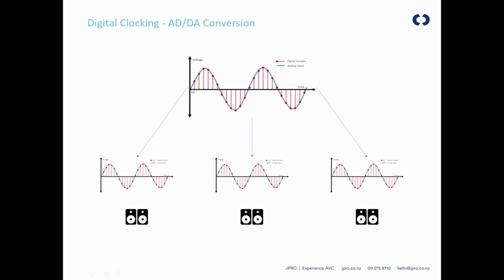So what happens in digital audio is that as time passes, samples get taken at reference points. And what happens with one audio form, so let's say this is my DSP playing audio now, it's digital, it has these sample points, so 1, 2, 3 as an example. What happens is that as it gets distributed across a system, be it a digital audio system or a network or something like that, other devices have to play out the same waveform. And it uses the same references.